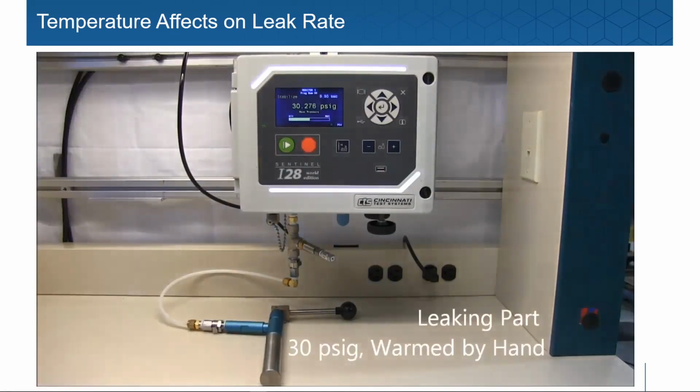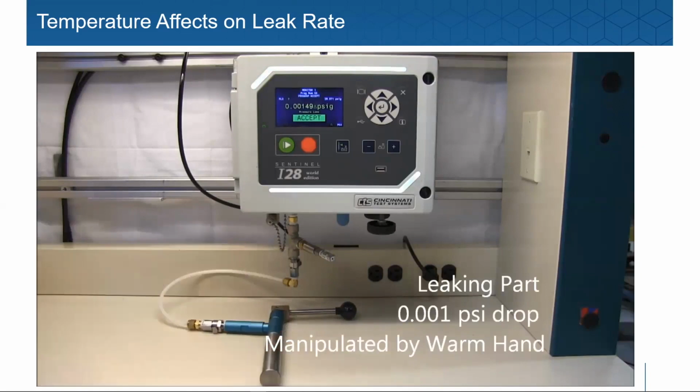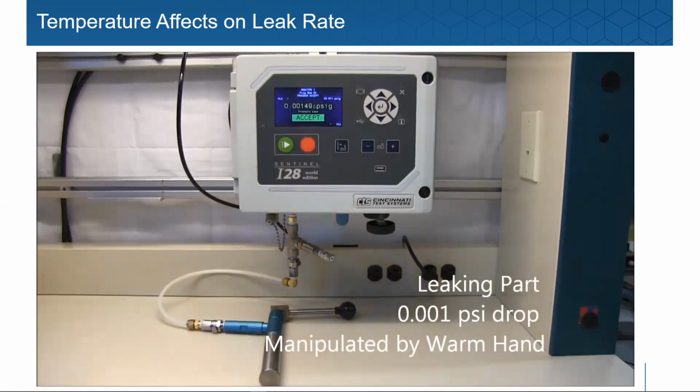Now what I'm going to do is actually put my hand on this stainless steel part just during test. It's all ambient conditions right now, but the minute that I hold on to that part, you see my hand warms it and masks a leak. So this 0.04 psi drop actually turned into a 0 psi drop because my hand warmed that part up and masked that it had a leak in it.